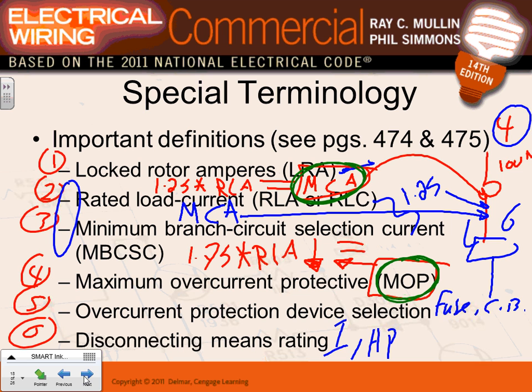We did calculation, guys. Is it different for the hermetic motors then? Here we're talking 225 for hermetic. If it doesn't work, very good point. If you use 1.75 times RLA and you're still tripping the circuit breaker, then you go to 225. 225 is the exception. This is the rule. Good point. If this system doesn't work, guys, we use 225. Any comments, any questions about this?